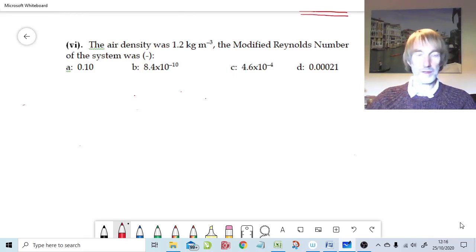In our porous media, it's going to be a little bit different from the flow Reynolds number down a pipe. Most engineers can remember that the Reynolds number in a pipe is d u rho over mu, where rho is the density of the fluid and mu is the viscosity of the fluid. Well, what do we mean by d? Well, that's normally the internal diameter of a pipe. Here though, in the porous media, we need some equivalent hydraulic diameter.